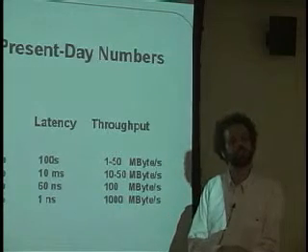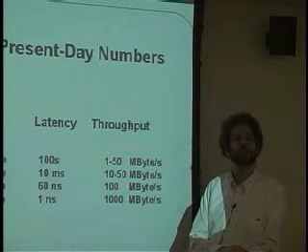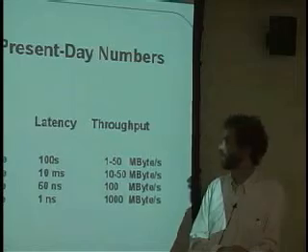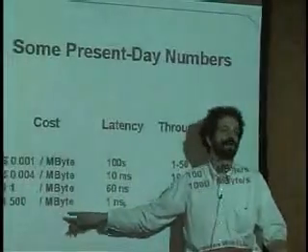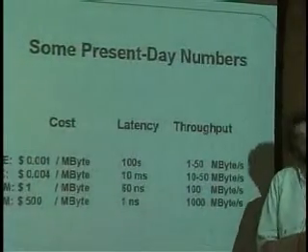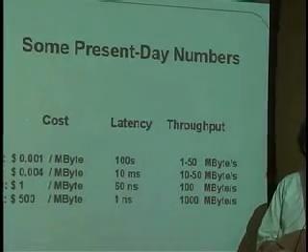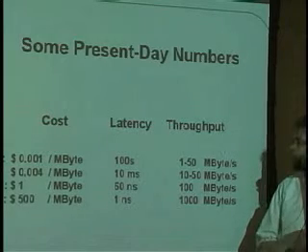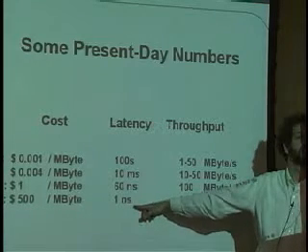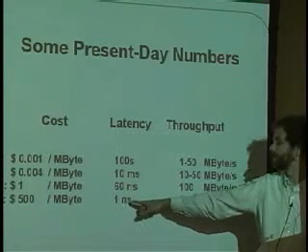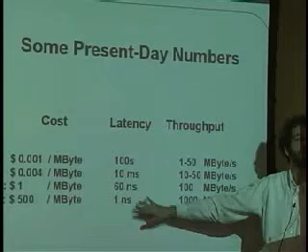Finally, we have this ridiculously expensive static random access memory. This stuff is typically on the actual chip that the processor is on. It's right there with it, and that's why it costs so much, $500 per megabyte, because typically you don't have a megabyte of it on the chip. You usually have a few 100,000 bytes of it, some fraction of this. So maybe $50 worth of the chip is devoted to the cache, to the static RAM. And lo and behold, we finally have a memory system that can keep up with the voracious demands of the processor and give a word out every billionth of a second. You can make it even faster than this, but this gives you roughly the orders of magnitude for these things.